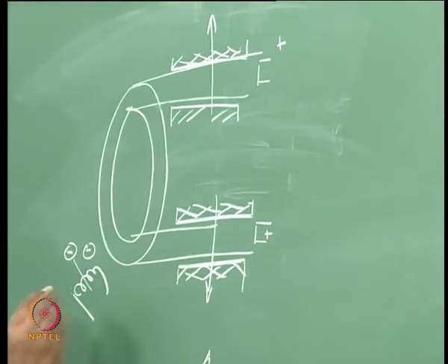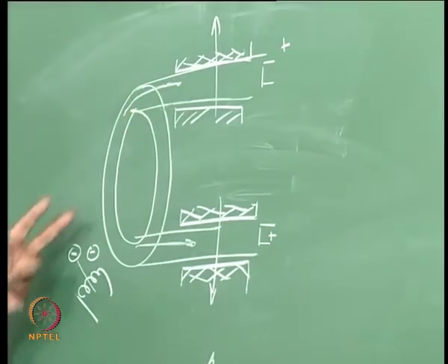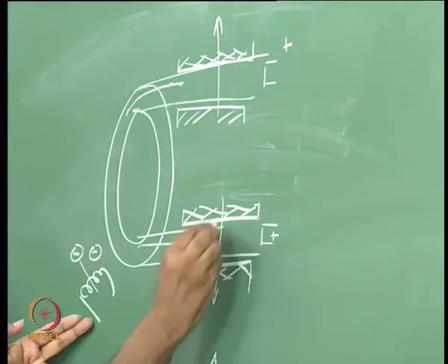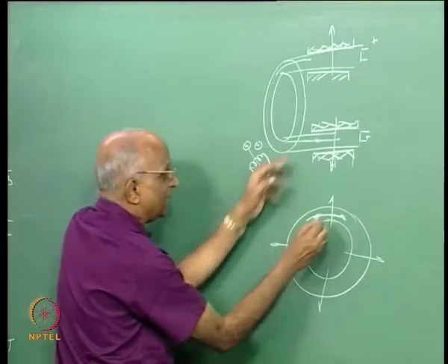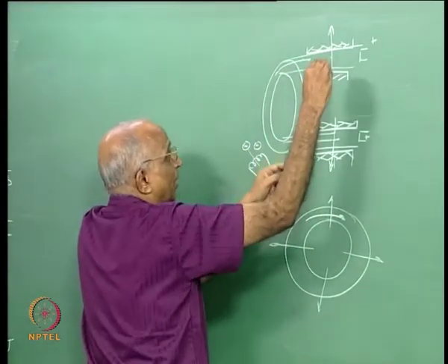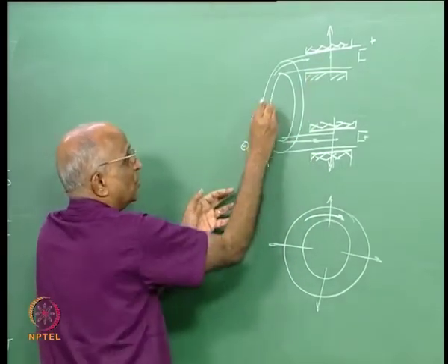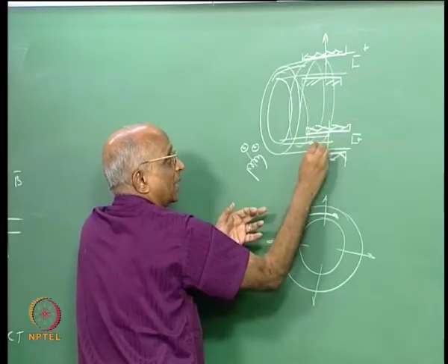The positive one is going to attract it in this direction, through the annulus it will go, and therefore electrons are moving in this particular direction, and the magnetic field is in this direction. Therefore, now I get a tangential force, normal to it, and therefore the electrons, instead of moving straight, will now move in a path which is spiraling here.